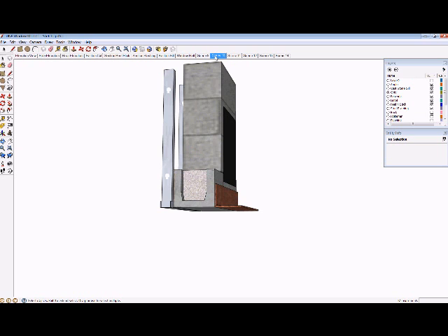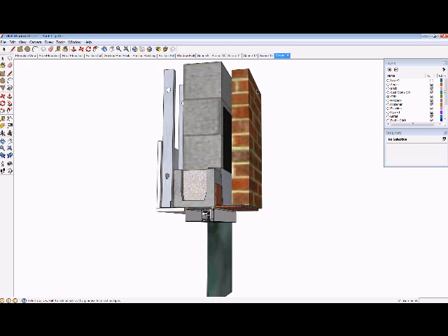So we'll put our peel and stick back on, then we'll put our flashing on, come back and put our window, fasten our window in place, seal our window with the manufacturer recommended sealants, and then come back and put the finishes in around it, the brick and also the drywall on the back side, and probably another beauty seal to the window. Now, as you can see, this isn't an extremely complicated model, but it does allow us to hash out and work through some issues that may come up that are tough to see in 2 dimensions.